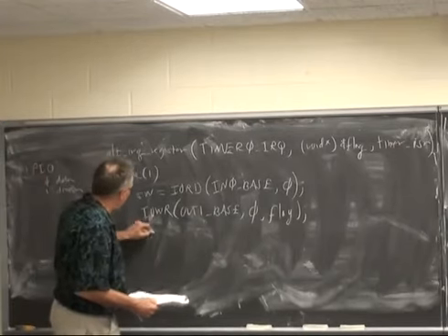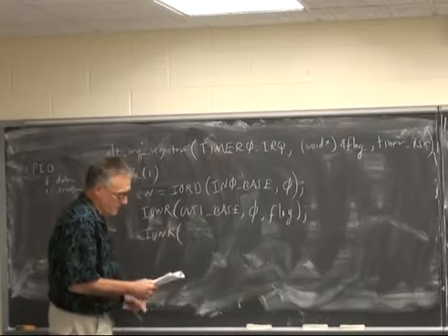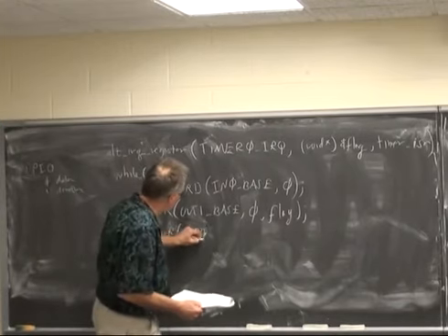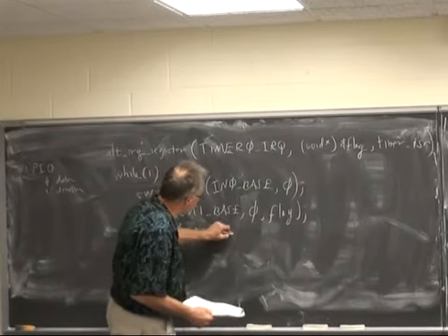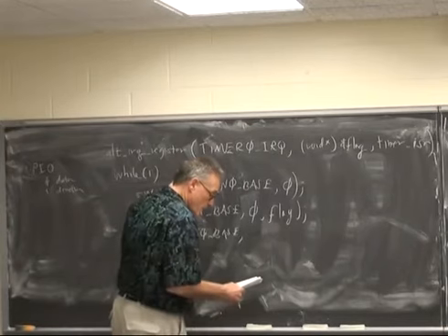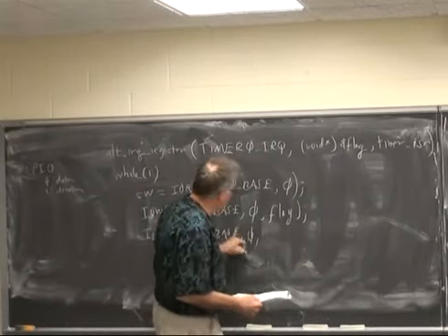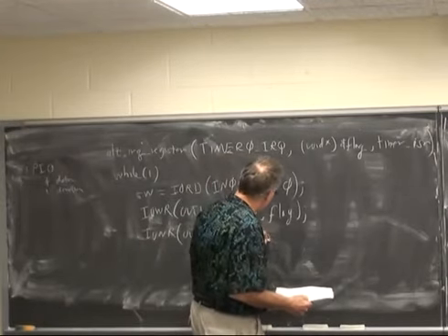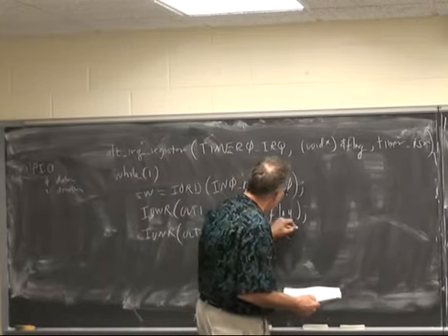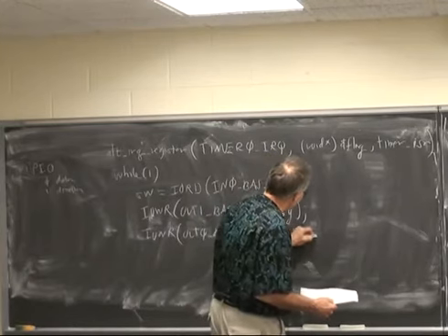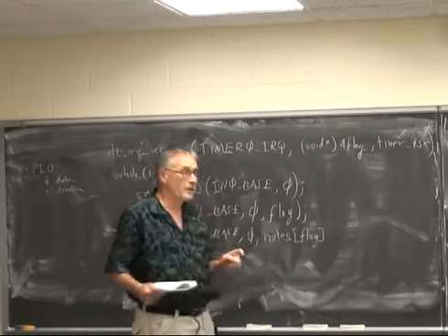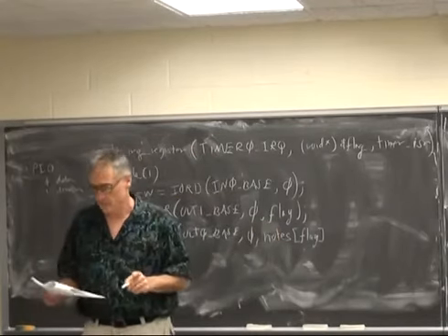Then we do an IO write to OUT0_BASE, offset 0, data equal to notes of index flag. So notes was an array of frequencies in hertz.